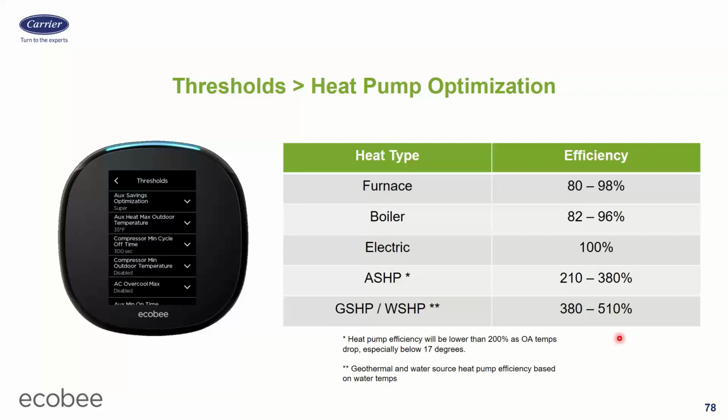Now, if your choices are running a furnace or electric heat, even though electric heat is more efficient than a furnace, usually natural gas is way cheaper than electricity. So you buy a furnace, and that's what we do a lot in our central market here in the central Midwest. But an air source heat pump uses the same fuel source as electric heat. They're both buying watts. They're both buying electricity to run. So there's never, ever, ever a reason to run your electric heater instead of running your air source heat pump. Always run the air source heat pump, and the electric heater is just there to supplement things when it gets freakishly cold. Because when it gets really, really cold, the heat pump can't get as much heat going.